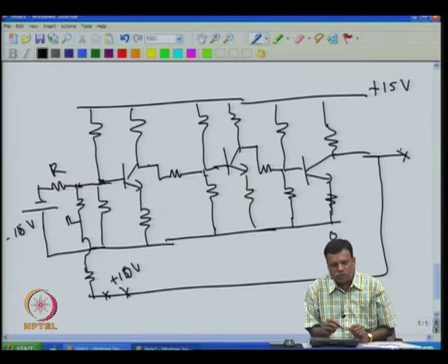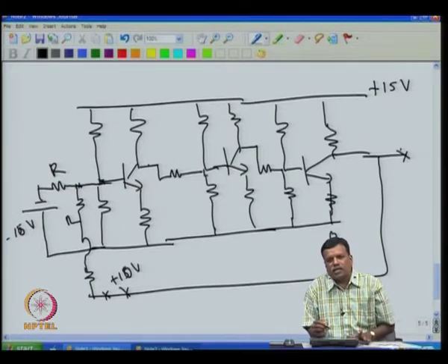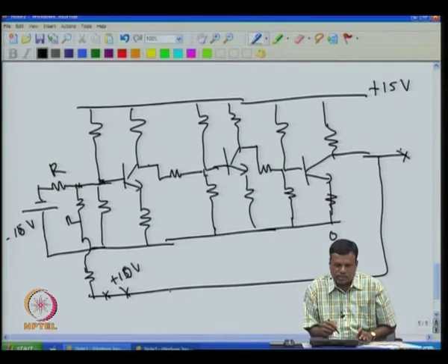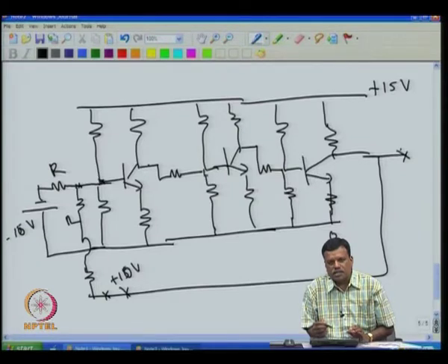That means it gives birth to the analog computer. You can sum two voltages, and in the same way you can subtract, or multiply, divide. If you perform all these functions, then you can develop a computer, and unless you have a computer you will not be able to develop a gun director. So, essentially they wanted to develop an analog computing machine and use it to hit these aircraft. They found that using this summing amplifier technique, if you have addition and subtraction, you can also perform multiplication and division and so on.